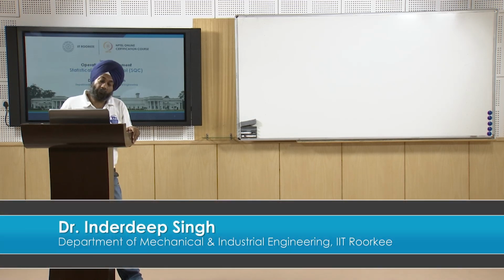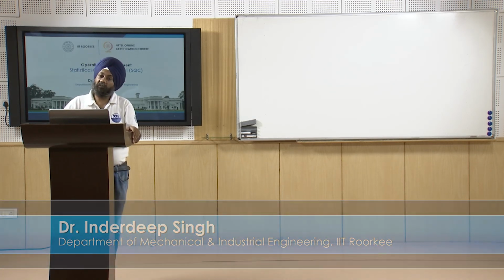So we first monitor the process, that is we collect the data, then we put that data on the chart and try to see whether everything is within the accepted degree of variation. If some of the values are beyond our control, then we try to improve the process performance over time by studying variation and its source. As soon as the variation goes beyond the control limits, we may have to stop the process and check for the causes, and then at the end try to improve the process in order to bring the process under control within the upper and the lower control limits.